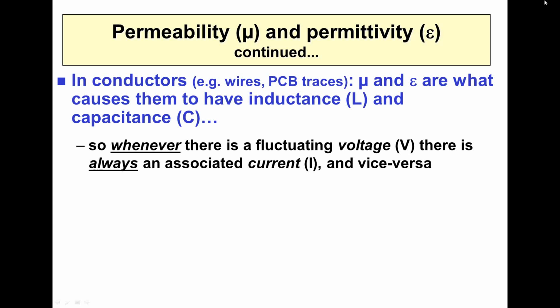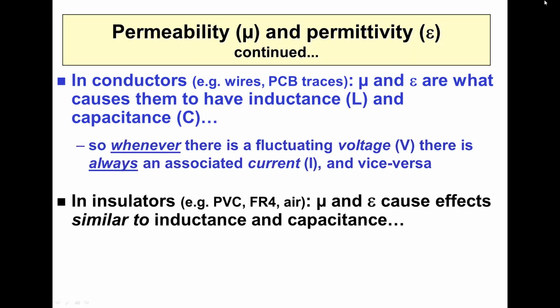Doesn't sound like a lot, but it is. And there's a significant capacitance associated with the trace. So whenever we vary the voltage on the trace, we have to supply some current. For the edges we use these days in digital circuits, that current can be measured in tens or hundreds of milliamps just to charge the trace up, which creates magnetic fields, of course.